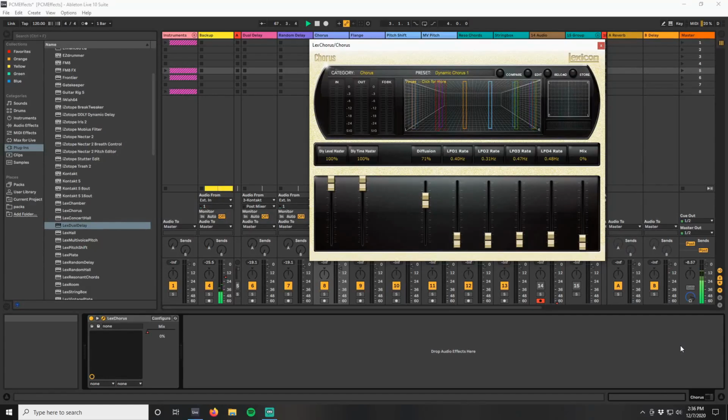For the chorus effect, the delay voices move somewhat independently, yielding a thickening effect without too much filtering. For the flanger, voices are generally paired at close intervals. As they move, a noticeable comb filtering will take place due to cancellation, and the voices are often fed back nearly to the point of instability.